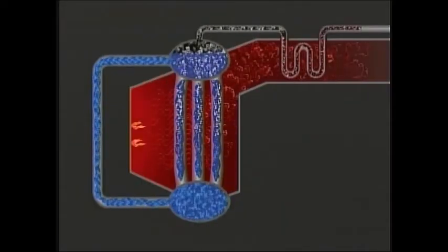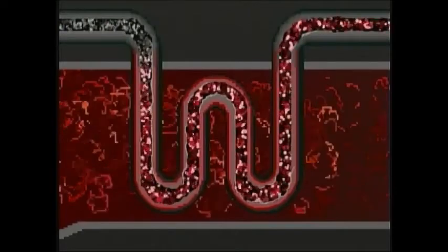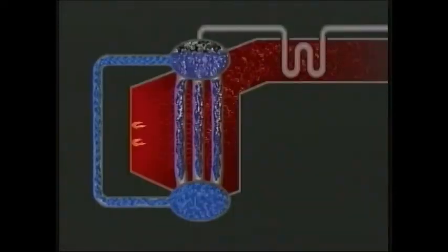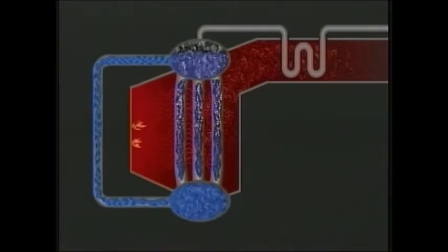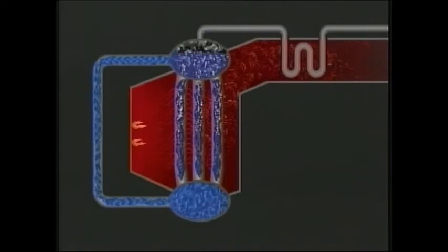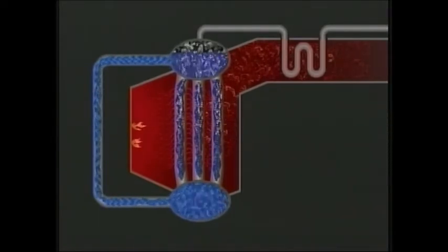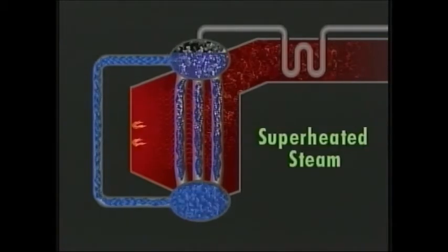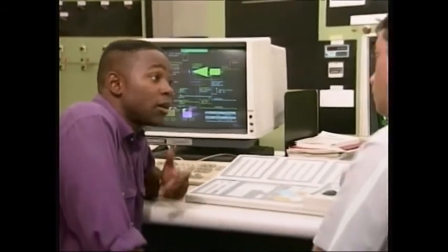In other boiler systems, like this one, steam flows from the steam drum through another set of tubes called a superheater. In the superheater, heat from the hot gases passing over the tubes is transferred to the steam flowing through them by a combination of convection and conduction. Since the steam is no longer in the presence of water, this additional heat increases the steam's temperature to greater than saturation temperature. Since this heat transfer causes a temperature change, it's sensible heat, not latent heat. Steam that is at a temperature higher than the saturation temperature for the existing pressure is called superheated steam. Steam can only be superheated when there is no water present. So you can see that a boiler is a good example of how temperature doesn't always reflect the amount of heat that a fluid contains.